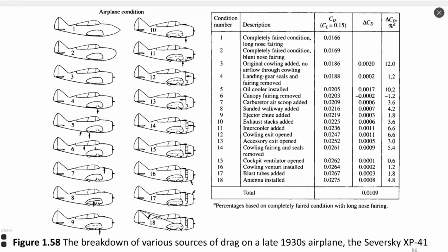putting some additional instruments, some additional devices that usually are directed against the flow or perpendicular to flow, they interrupt the flow, disturb it, and they have their own drag coefficient, quite a big drag coefficient. But since these objects, these tools are small compared to the whole airplane, this change of total drag coefficient is not so significant, but is sensitive. Starting from the completely clean airplane, which has no additional instruments.